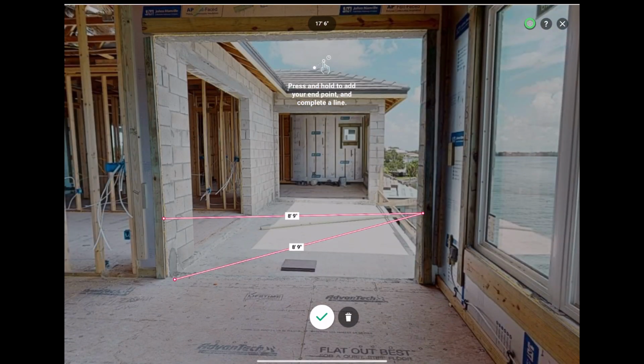Here in the top right hand corner, there's a little settings menu, and here you can turn on a couple features. Snapping kind of gets you to the closest point. If you find that it's trying to start the point somewhere where you don't want it, you can just turn snapping off and you have a little bit more accuracy. Continuous lines, you can see here, is what we're looking at, where it will just build off of the next point.